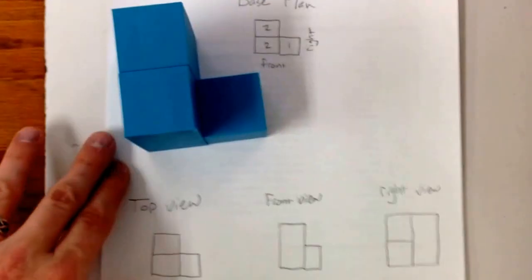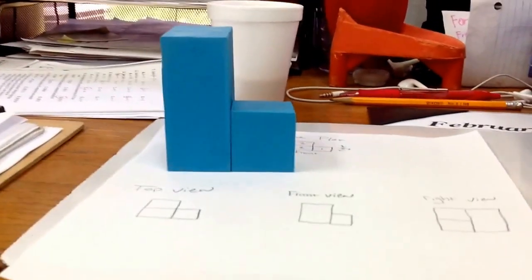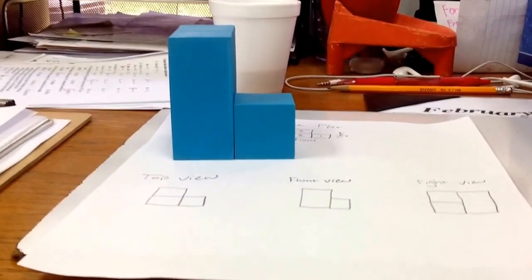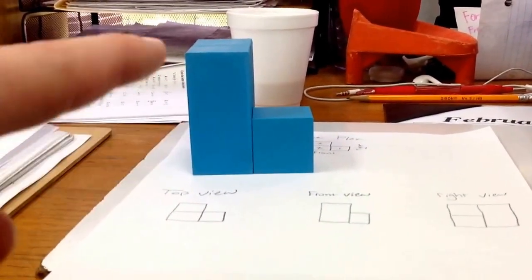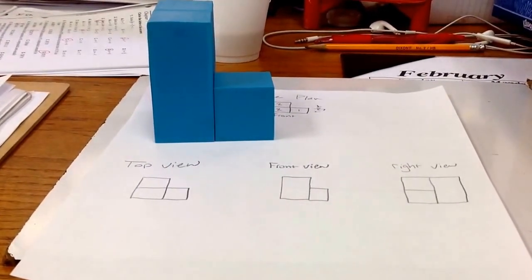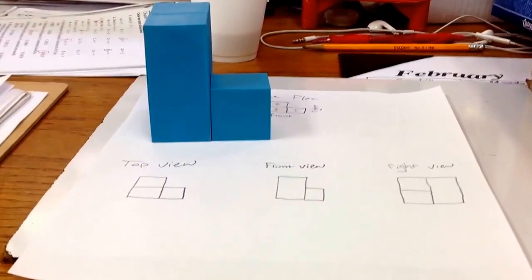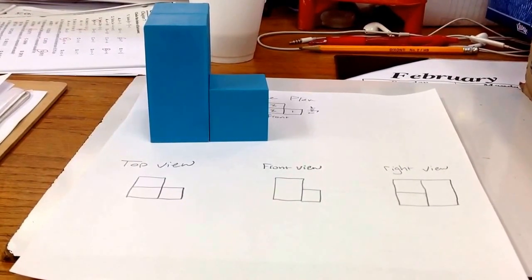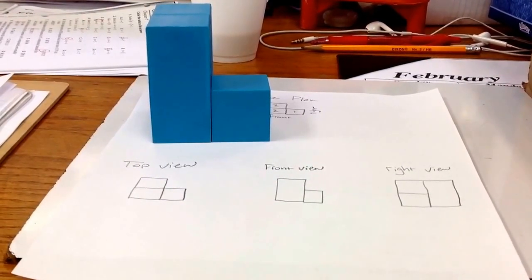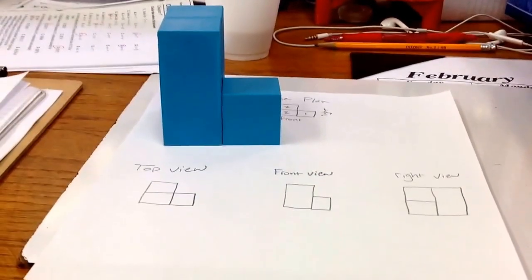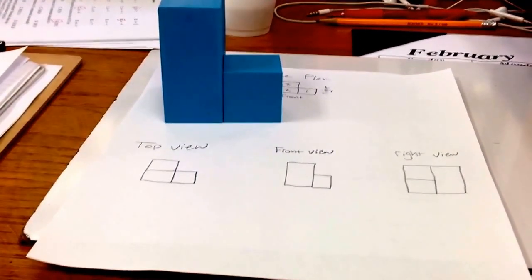Then the same from the front view. So if I'm going to move and look at the figure just from the front of the shape, it still has that L shape, but notice that there isn't a separation between these two blocks anymore, because this is just one big block. So when I draw my front view, you can see there, right there in the middle, I don't have to have the separation of the blocks. I would only separate it or draw the lines in my shape if it's a different block. If they're connected, then I don't have to draw those lines there. So the lines in this case help to show if the shape has an attachment or not.